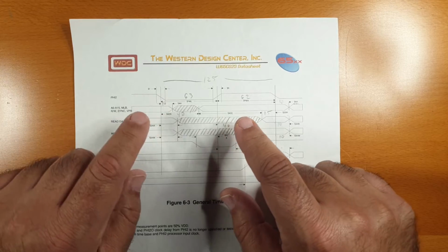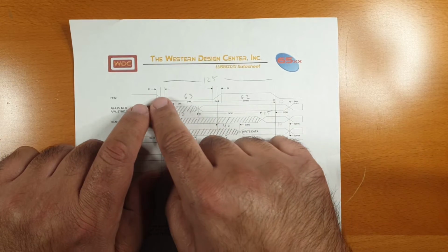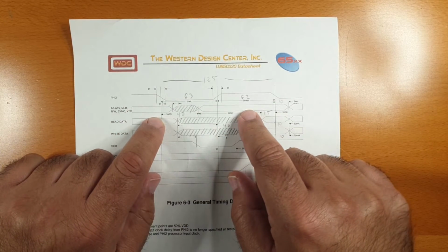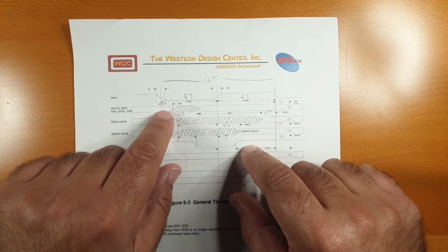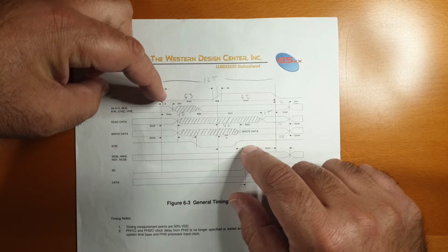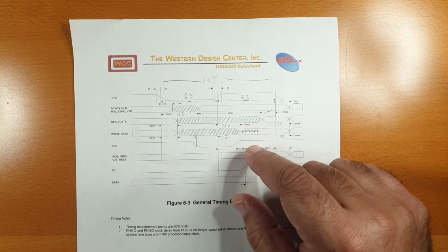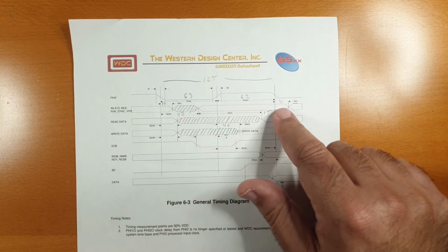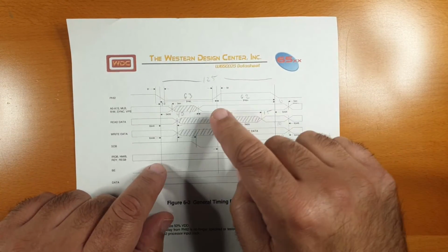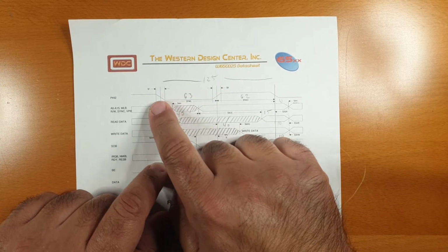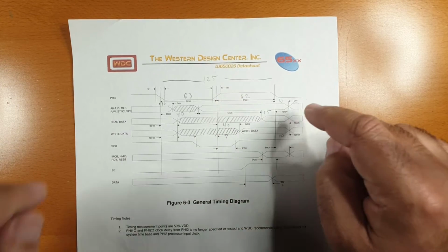So in case we need to output from the program counter, the falling edge is what triggers a change in the address, but the address needs to remain valid until 10 nanoseconds have passed. So in this entire area, the address needs to be valid. And we're not allowed to latch the values between the program counter and the output. What all those in tandem tell us is that the program counter has to be updated on the falling edge of the clock. We cannot update it on the rising edge of the clock because then this timing diagram would not be possible.